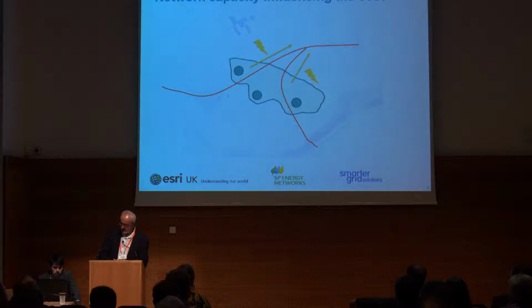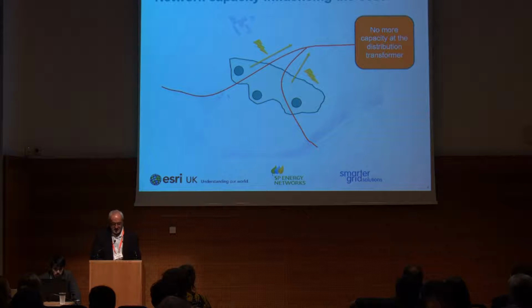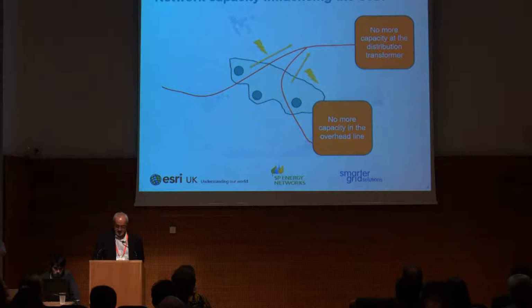Limiting factors very much revolve around generator output voltage at the point of connection to our network, which may require laying cable towards the source primary. The other limiting factors are the size and type of conductors that exist on our network, and existing generation on the same circuit or interconnected at that primary source. It may be that the primary or secondary transformer to which you're going to connect has no further reverse power capacity. These will influence the cost.